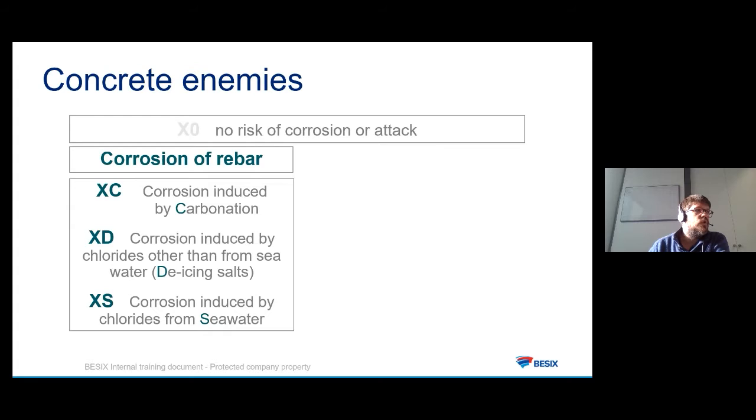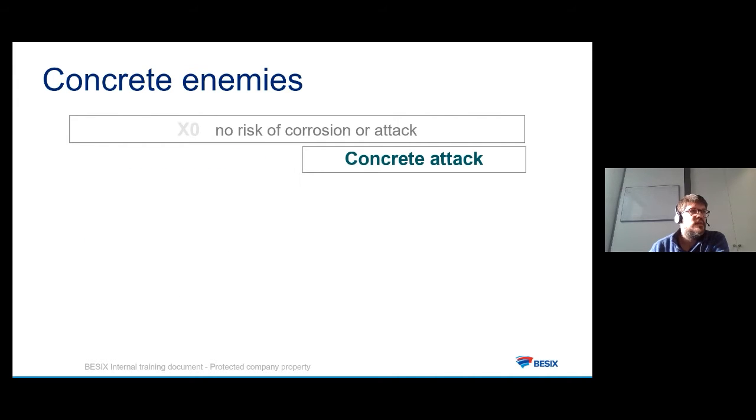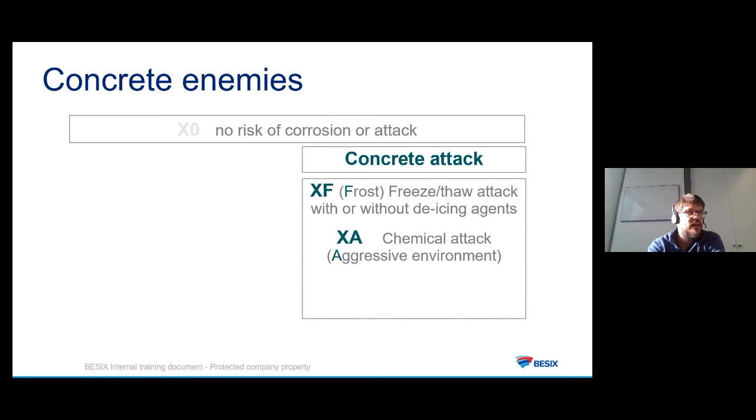On the other side, you also have the concrete attack. This can happen even for non-reinforced concrete. And then you have the XF, related to everything to do with freezing, with or without de-icing agents. Of course, this is mostly important for countries where you can have freezing. And then you have the chemical attack.